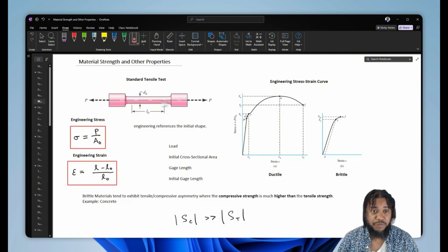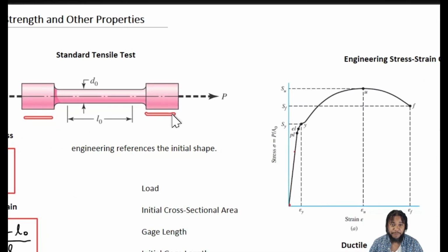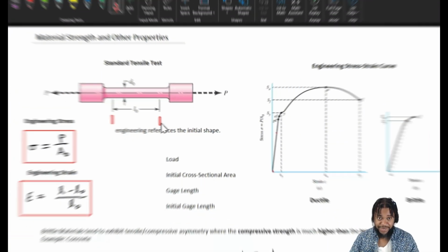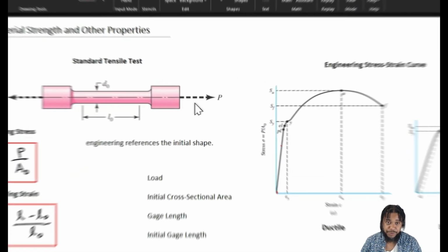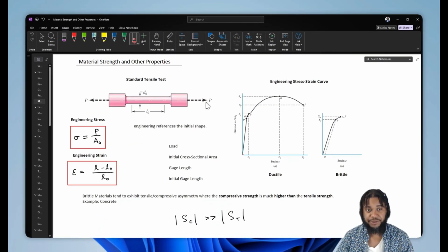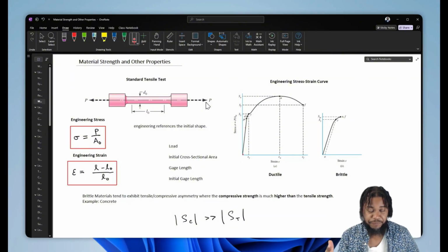And so most often we'll design a tensile sample. We'll subject it to a fixed displacement rate, and we'll record the force that builds up in that part until it fails. Now, at that point, we have force data and displacement data over time.